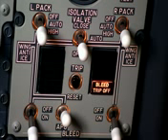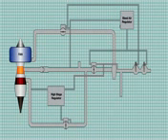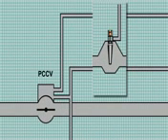Now that we've seen how the bleed air system controls pressure, let's see how it controls temperature. As we saw earlier, the pre-cooler is an air-to-air heat exchanger that uses engine fan air to cool the bleed air. The pre-cooler control valve, or PCCV, and the 390 sensor control fan air to the pre-cooler.